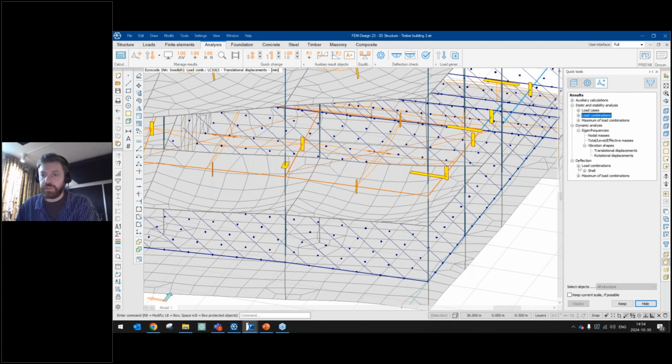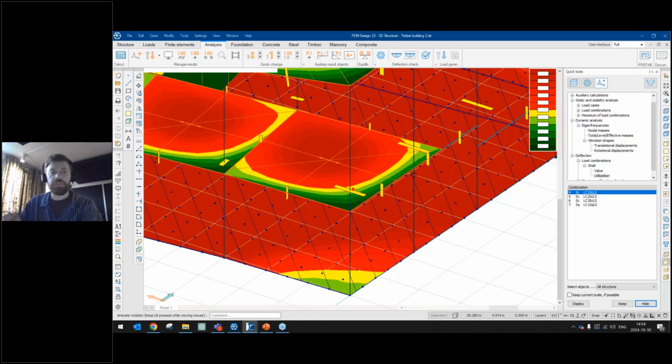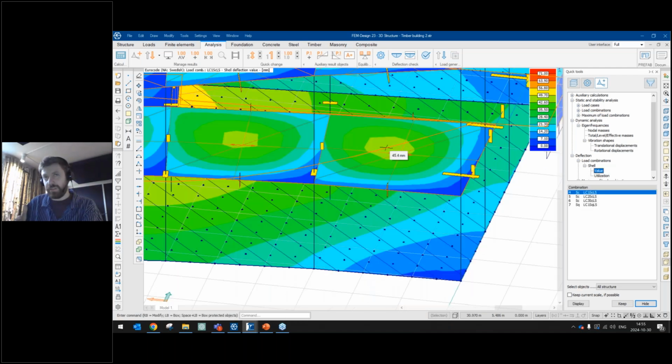And I can take a look at the utilization for deflection, for example. Here I don't actually fulfill my criteria. I have much more deflection, so 227% overutilization. And I can see the value here, which is the relative deflection. You could see before that I had a total deflection of about 116 or something like that. Now it's actually 45 millimeters, which is the actual deflection of this, subtracting the deflection of the global influence, if that makes sense.